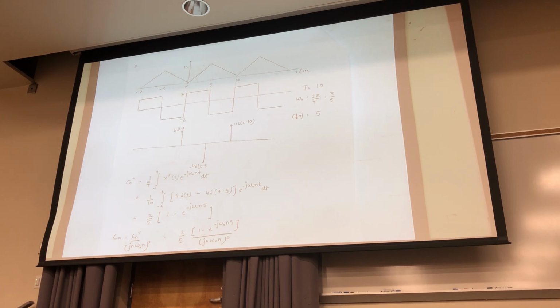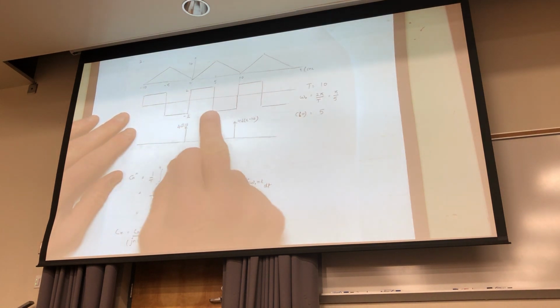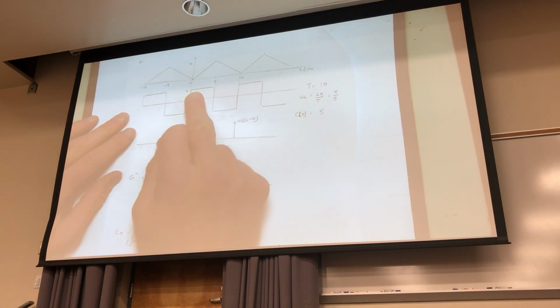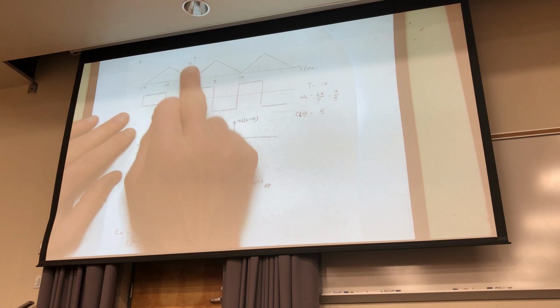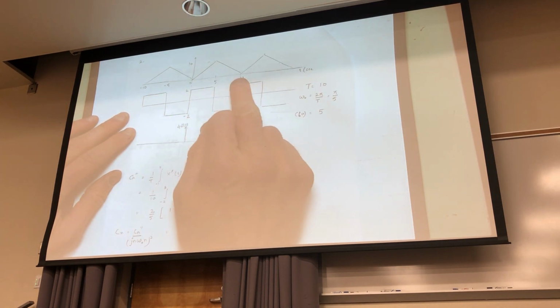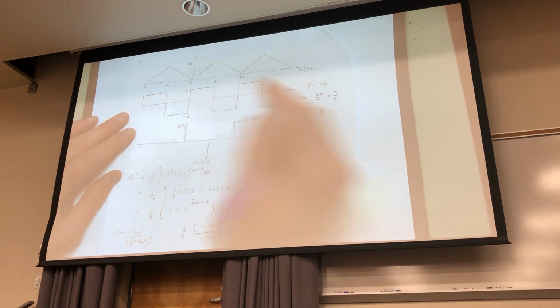So you're going to take 2 derivatives. First derivative, you get a square wave. And the square wave's height is just the slope. If you go from 0 to 5 with a height of 10, the slope would be 2 there. From 10 to 0 with a scale of 5 seconds, over 5 seconds, that's minus 2. Then you take a derivative of that, and you basically get this.